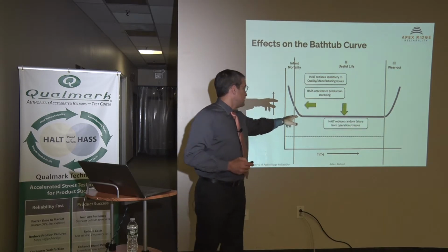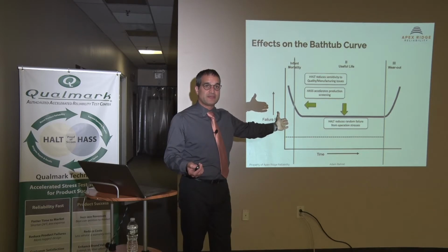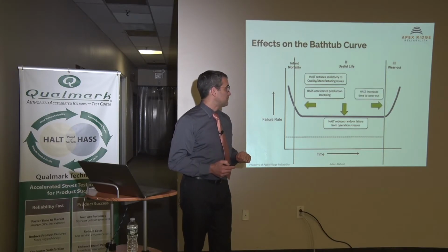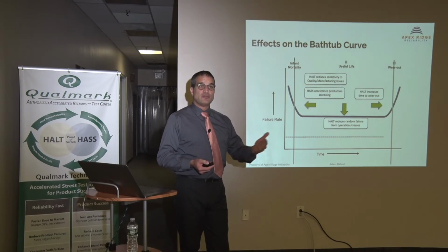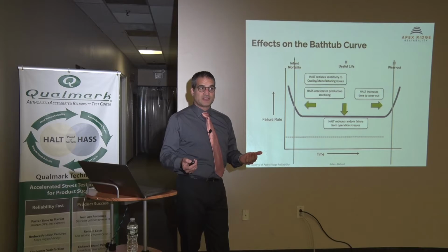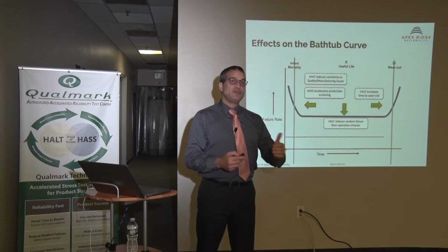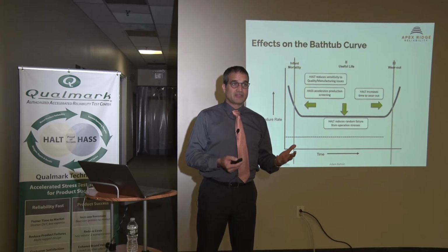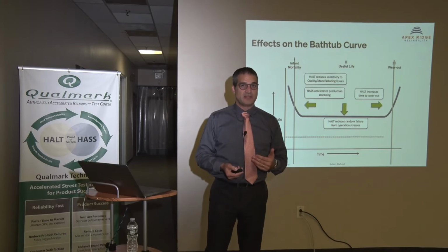Next, it will reduce the sensitivity to stresses during use life. We've created that margin. So now the stresses that drive that random failure rate affect a much smaller part of the population. So we've lowered the center part of the curve. And then the last is it increases time to wear out, because wear out is accumulated stress that causes a performance issue. So if we created more margin, it's much more likely that if accumulated stress causes that failure, you have more of the strength of the product to go against that accumulated stress, and it can last longer.